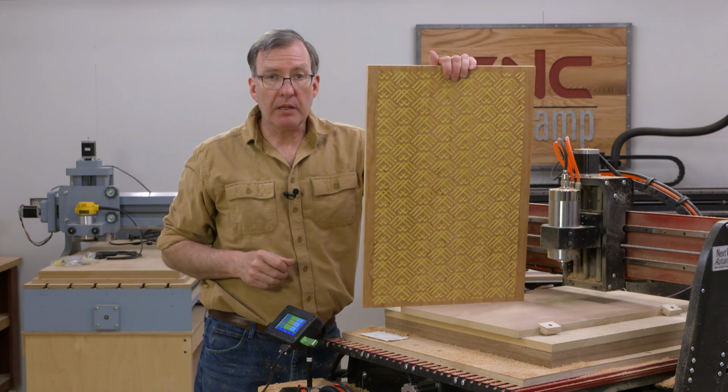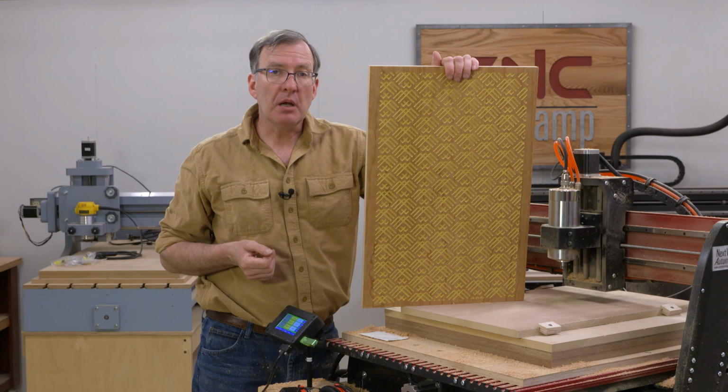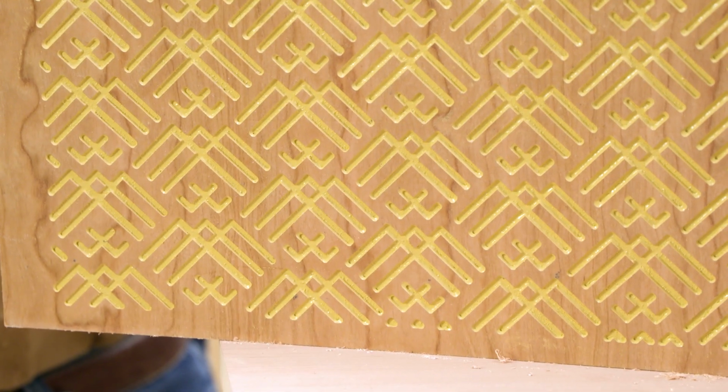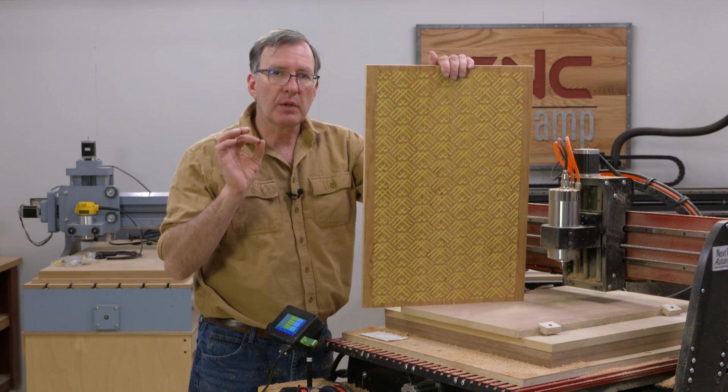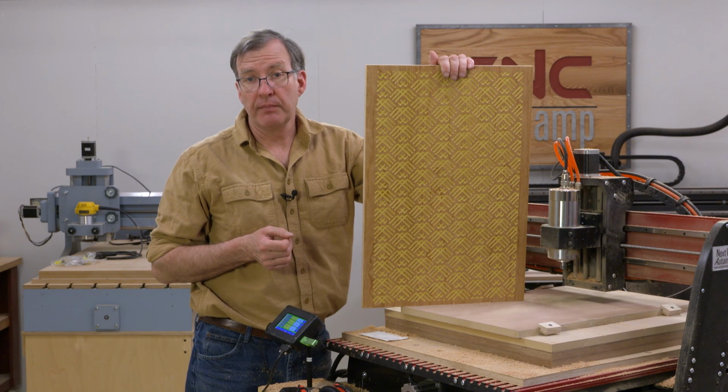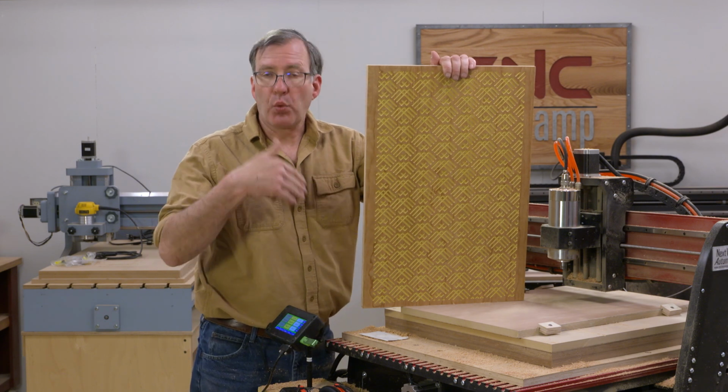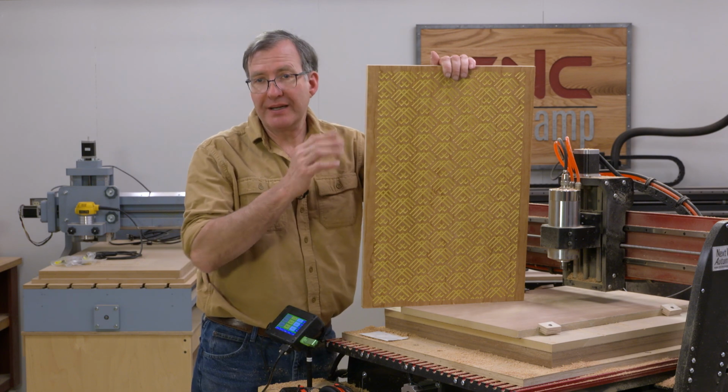So this is the same panel, but I've added some Sunglow yellow to the recesses. What I did was just took my brush and basically stippled it in there, being very careful to make sure that all the area was covered. I then took a rubber float like you'd use for grouting tile and squeegeed off any of the excess paint. I let it dry overnight, then I came back and using my orbital sander, I resanded the surface. That surface had previously been sealed with lacquer so the yellow paint didn't penetrate. Once I'd resanded, I then re-lacquered, and that makes everything bright and clean again.